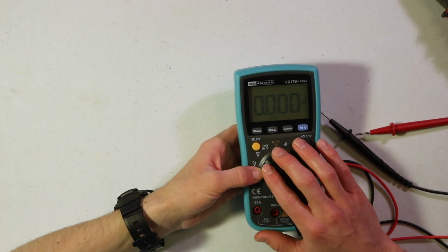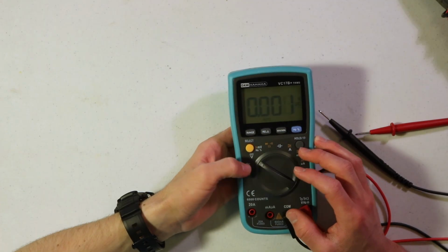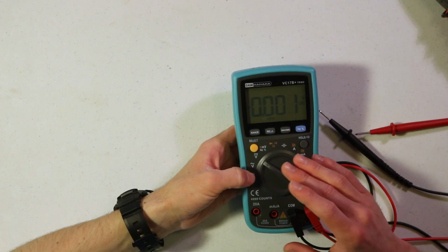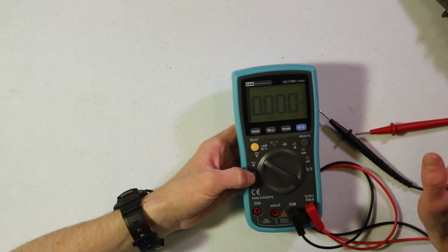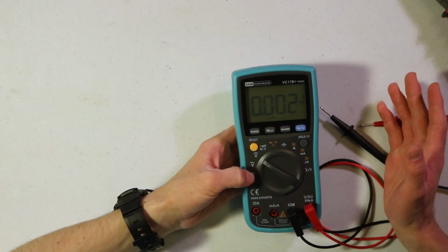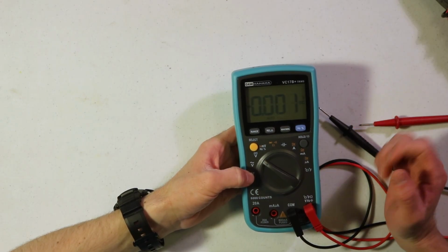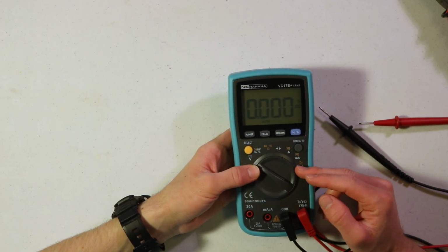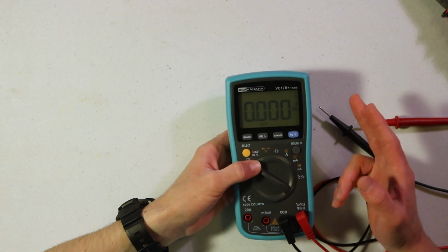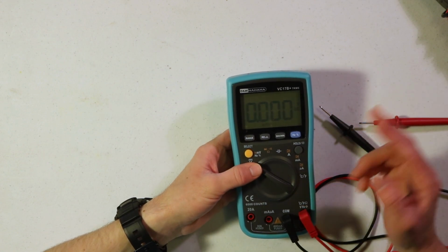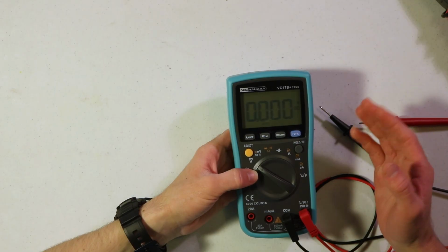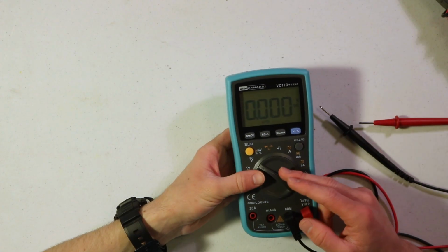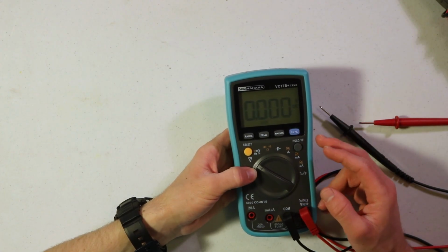And for other ones where they have more options, then instead of just having two settings here for volts and millivolts, they might have up to 2 volts, or up to 20 volts, up to 150 volts, or whatever. So let's say that you wanted to measure something that was 5 volts. Well, then you couldn't do the 2 volt rating because that's too low. It wouldn't go up high enough. So then you'd have to go up to the next one up, which maybe would be 20 volts. So that would just mean you could go up to 20 volts, but you don't have to go up that high. So if you have 5 volts, that would fall within the range of 2 volts to 20 volts, and then that one would be the correct setting to use to measure that.